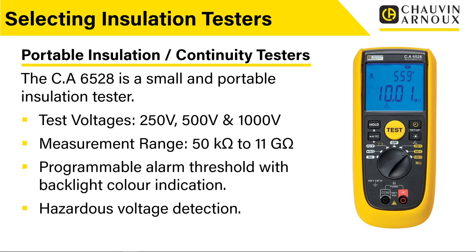Now this will carry out testing particularly suitable for the normal low voltage type insulation. So it'll do test voltages of 250 volts, 500 volts and 1000 volts DC. It's got a really wide measurement range, which goes from 50 kilo ohms all the way up to 11 giga ohms. So we're talking way up, above mega ohms, we're into giga ohms. So it's got a really wide measurement range there.